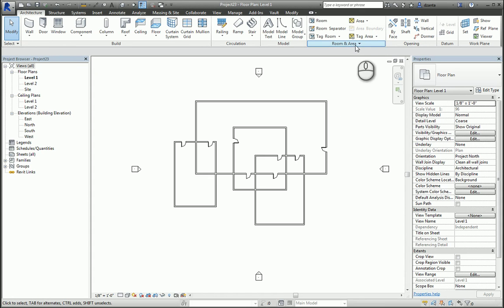What is a room in Revit? A room in Revit is an object. Think of it like a cloud that you can hold in your hand. When you take that cloud and move it into a space and let go, the cloud will expand and grow and envelop the space. It will stop where it hits all these walls, and walls, floors, ceilings, roofs, and certain other system families have a feature known as room bounding, and when that feature is checked, these objects know to stop a room object to help define the room object in regards to length, width, area, and volume.